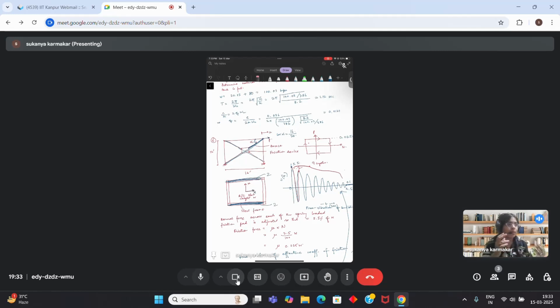Now in a building also, suppose there is a reinforced concrete building and some earthquake hits, there can be various sources of energy dissipation. There will be cracking in the building, that can be a source of energy dissipation. So it is a difficult phenomenon to put into numbers. We introduce the concept of viscous damping. So when do we use the concept of equivalent damping? Suppose in the lab you do a certain test and you draw the hysteresis plot, and you come up with